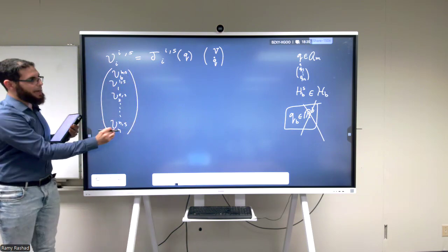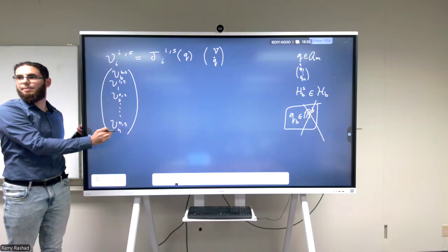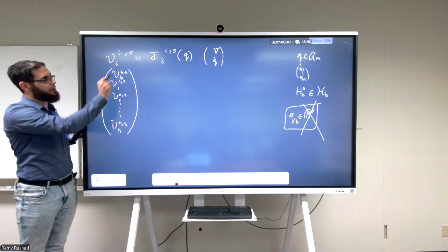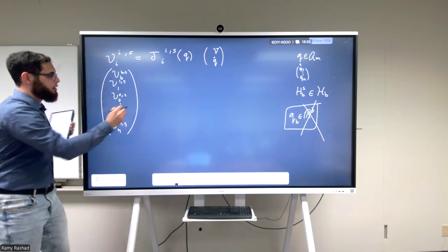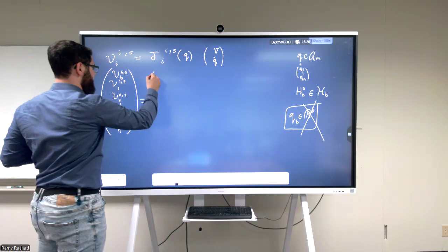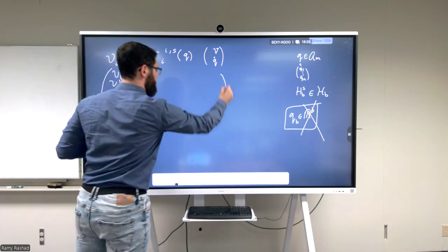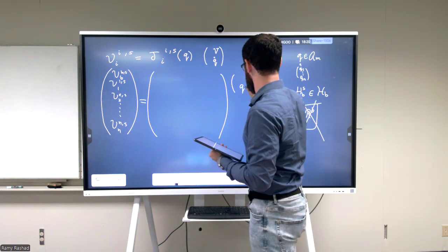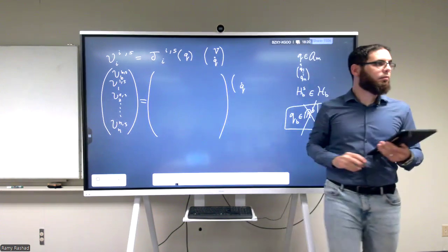From here to here, we had that before, right? When we had a fixed base manipulator, we had from 1 to n. We had n links. So we had all of this. This is just the extra step. And we wrote this as a big Jacobian matrix multiplied by Q dot, right?